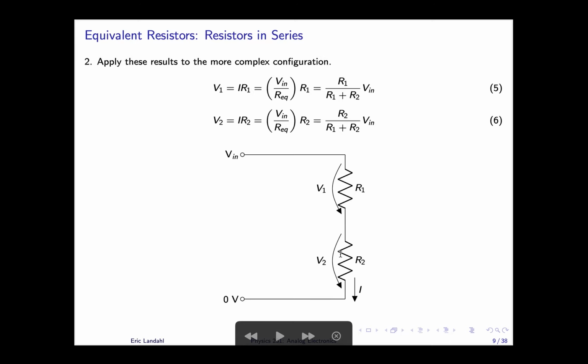Let's look at the other equation for a moment. Let's say again R2 equals 0. What should V2 be? Well, we know it's connected to ground, so the answer should be 0. We'll check it. It makes sense if we put a 0 here in the numerator for R2, this entire expression is 0, multiplied by V in is still 0, and V2 is 0. And I'll leave it as an exercise to the students in this class to verify in their own minds that, furthermore, if you were to take an R1 value equal to 0, that is, replace this first resistor with just a wire, you would also end up with reasonable answers for what V1 and V2 should be.